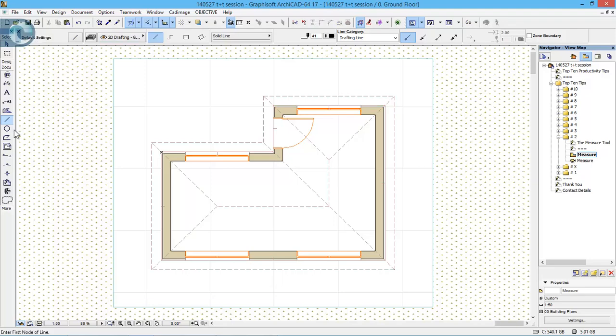So I've seen other people, rather than do that, they'll maybe draw a circle, or start to draw a circle, hit escape, draw one from there to there, check that dimension. But there is a risk with this that you forget to delete elements, which is never going to be a good thing. So the proper way to do it is to use the measure tool. It's actually up here as a little ruler, and all you do is click on one point, rest the mouse on another, and we get to read the distance, the angle, and the X and Y coordinate.